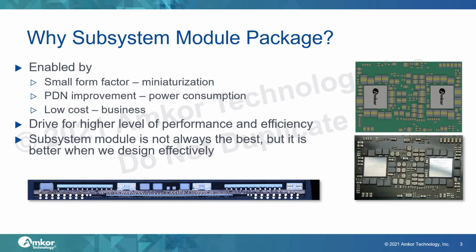Specifically, the design of package form factors should include careful consideration of optimal PDN performance and the number of components, which need defined decoupling capacitor value and the placement strategy for low impedance profile with cost benefit.